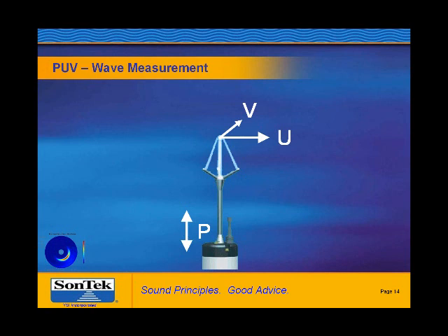Again, as we discussed, waves are a disturbance of the surface of the ocean, and they travel in time and space. As they propagate throughout the ocean, the displacement that they cause on the surface is felt not only at the surface or just below the surface, but also at depth. Now, data from a high accuracy pressure sensor records this change in the pressure, which is what is shown here as the P in the slide.